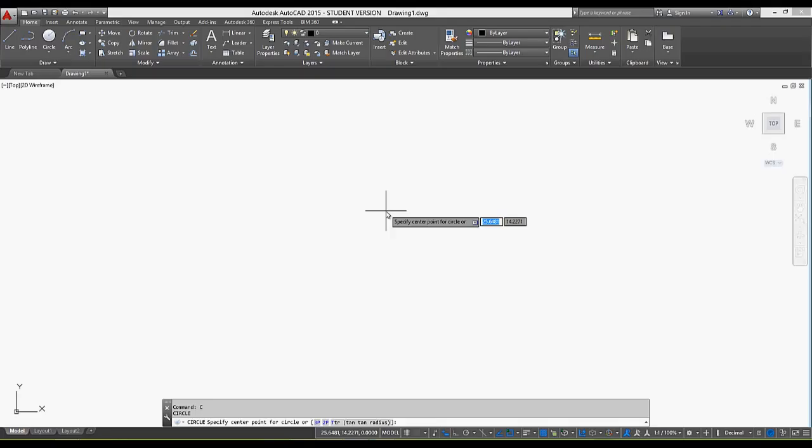So you'll find that when you start to work with AutoCAD, a lot of things are one word. If something that should be like 3 separate words is now one word, that's because the spacebar means enter. Or you'll see it in underscore too as well. So you can also type in the command, and you can hit spacebar.